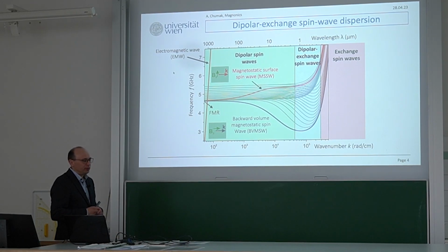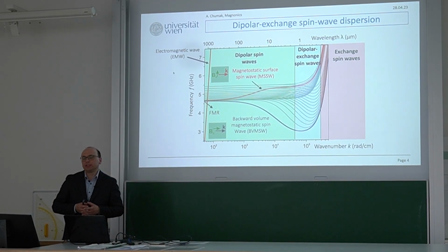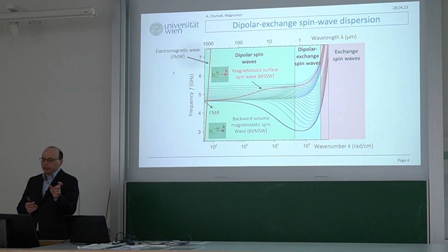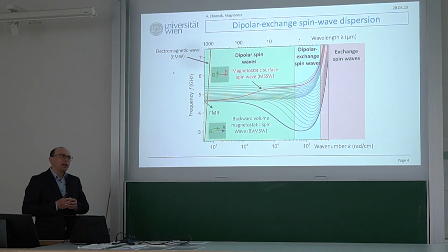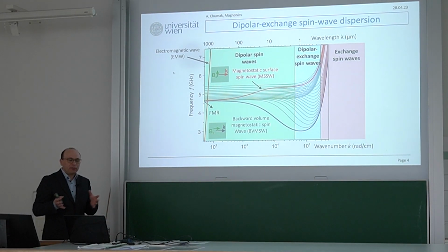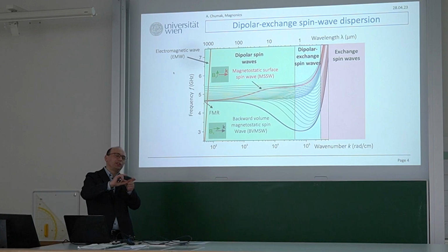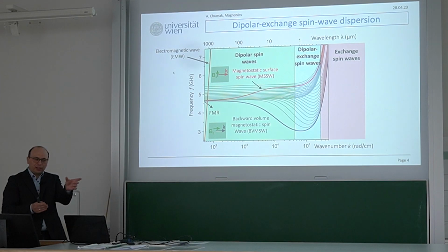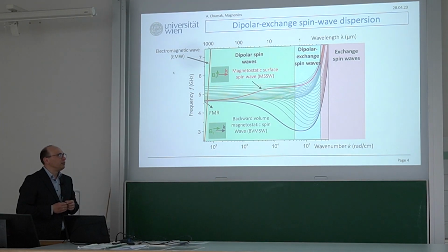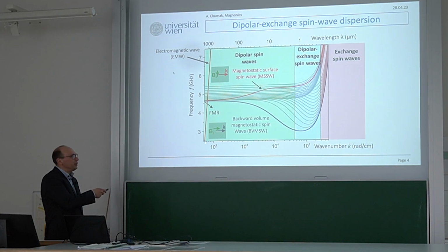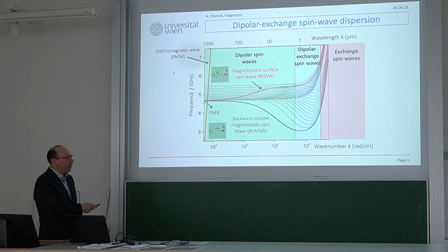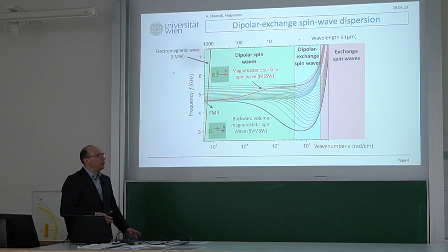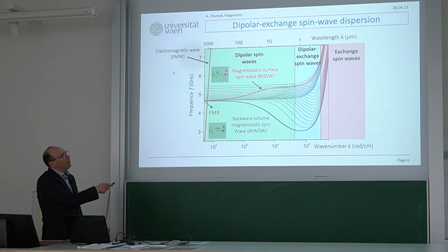So it's centimeter-long wavelengths of electromagnetic waves. If you go to our lab and take some attenuator, the size of waveguide scales with the wavelength. So if you have attenuator for 4 gigahertz, it should have such a big waveguide. It means that wavelength is larger. Then if you go to 10 gigahertz, it's getting smaller and so on. But wavelengths of spin waves can go from centimeters down to microns. Therefore, what we see is that spin waves have much shorter wavelengths for the same frequencies.